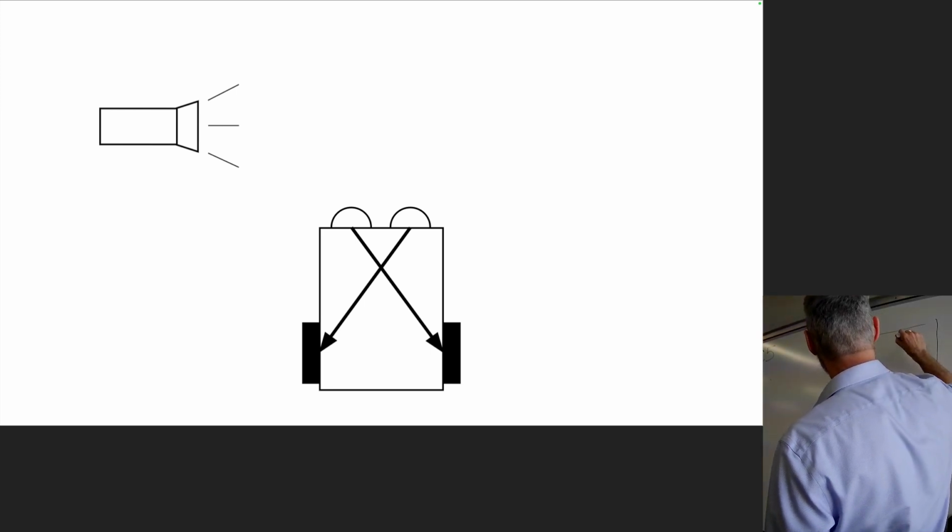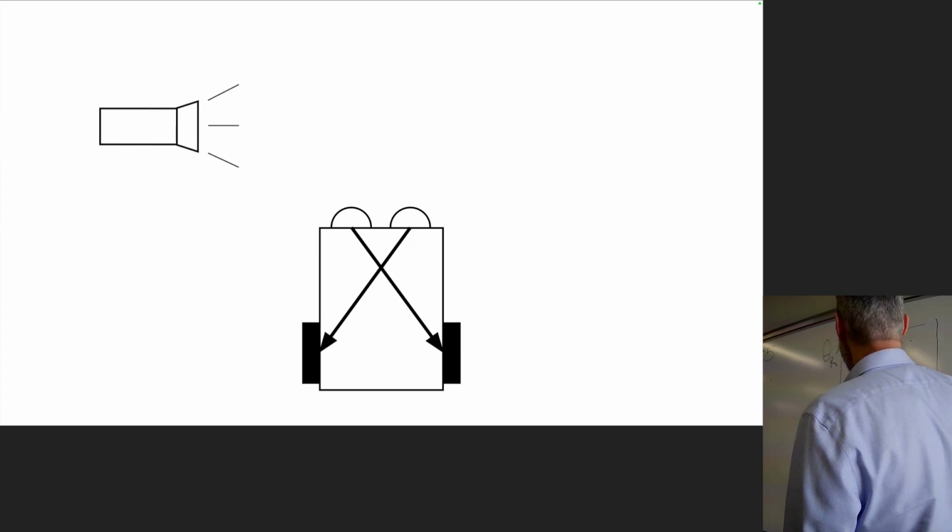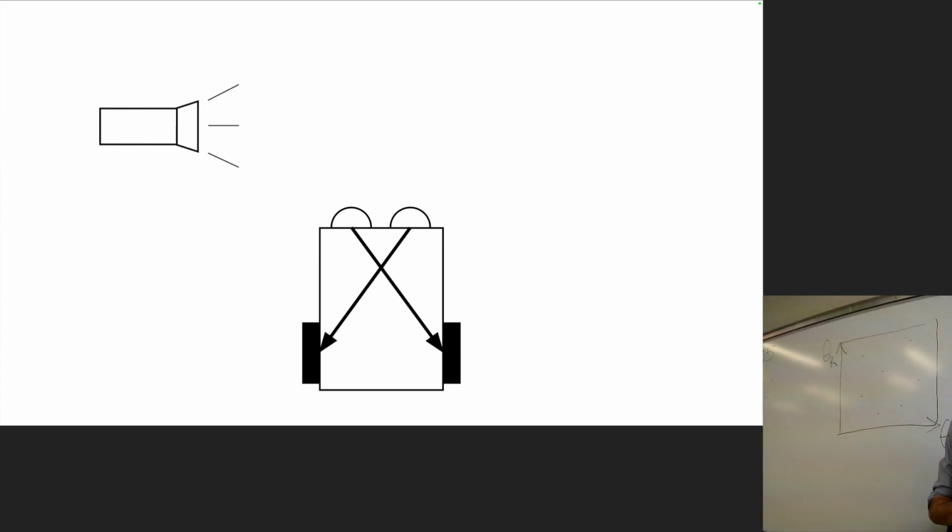We might start by creating a population of random pairs of synaptic weights. Each one of these points represents a genome. We take that genome, or that pair of weights, drop it into the vehicle, measure fitness, and we have the height of the point. Let's assume a higher value is better.